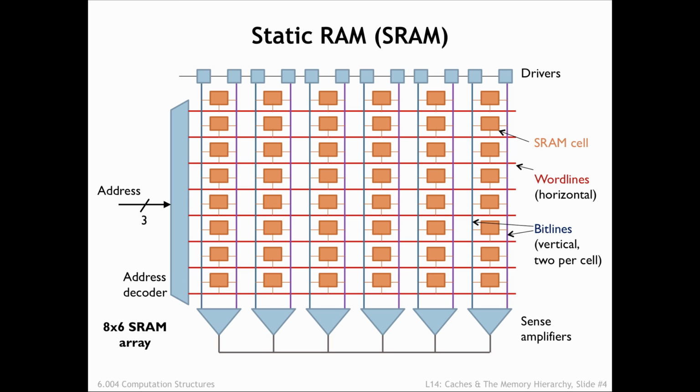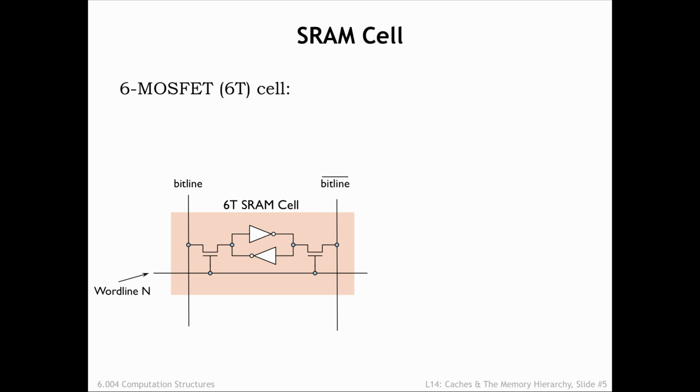During read operations, the bit lines carry the analog signals from the enabled bit cells to the sense amplifiers, which convert the analog signals to digital data. During write operations, incoming data is driven onto the bit lines to be stored into the enabled bit cells. Larger SRAMs will have a more complex organization in order to minimize the length, and hence the capacitance, of the bit lines. The heart of the SRAM are the bit cells.